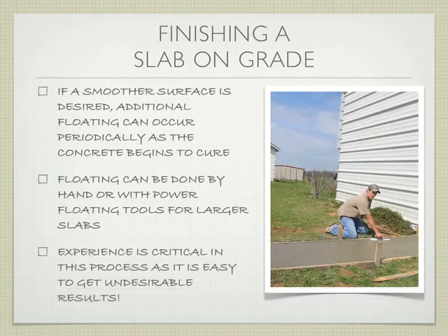So if you want a smoother surface, you're going to do an initial floating periodically as the concrete is beginning to cure. And this is the kind of thing that really takes somebody who's done it and is experienced to know the right moment when to do it, because that right moment isn't a pre-programmed thing. It's not something you can say, oh, well, 1 hour after the first float, I have to do the second float.